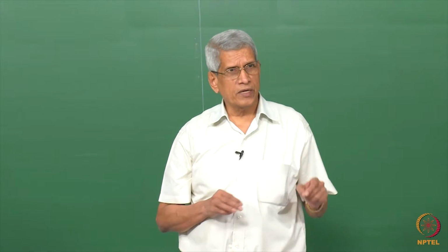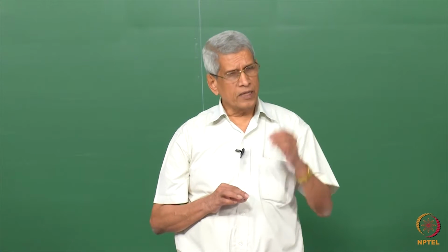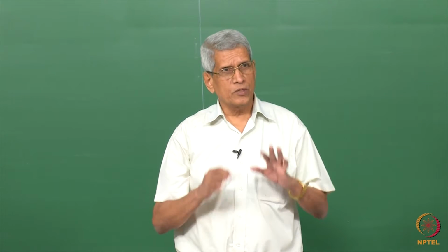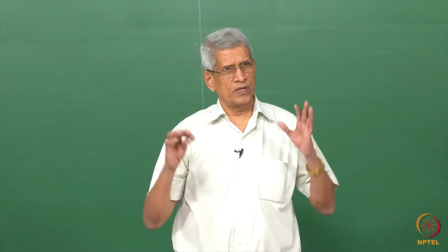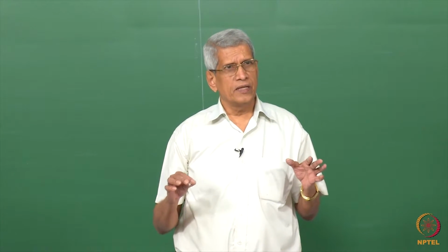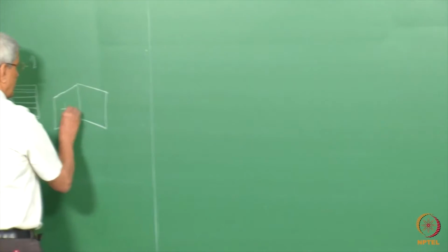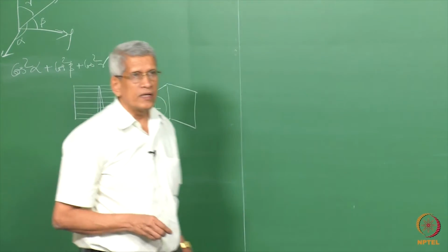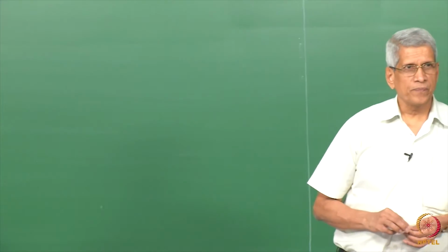What is the other important characteristic whenever we consider a grain boundary? Another important aspect is that if we assume that these boundaries are made with dislocations, generally we know that when dislocations are present, there are long range stresses. If a dislocation is present here, the displacement field will be there all over. The long range elastic stress is there, over large distances.